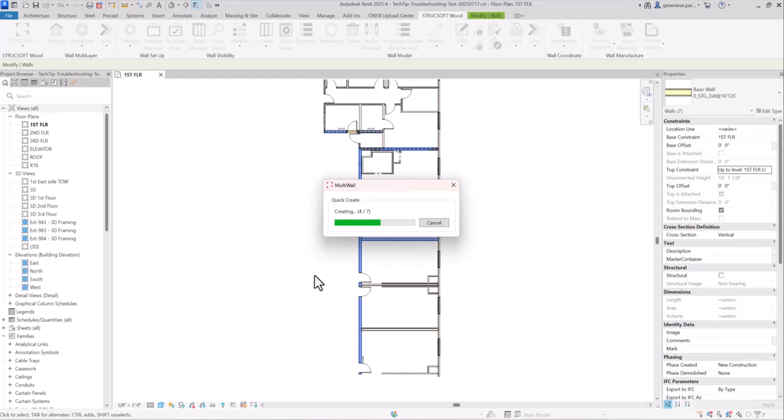That can definitely narrow down if it's an issue that is part of your user created template, or if it's something else. Now you can also open up a clean new project file and test all of your templates within it. Or you can also test all the default templates to kind of narrow down, is it a template problem? Is it a Revit problem?